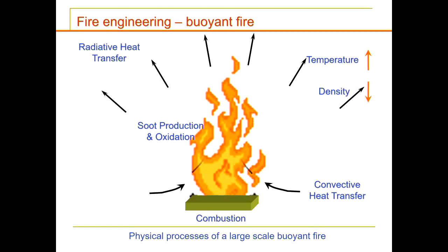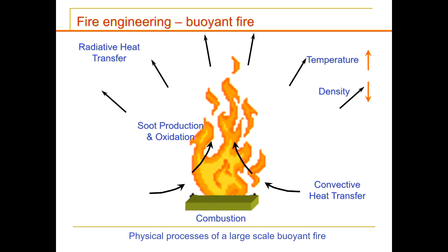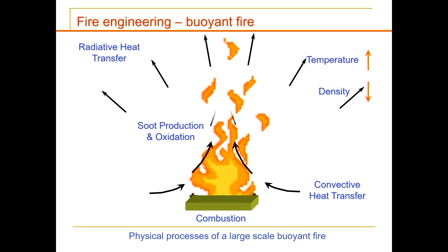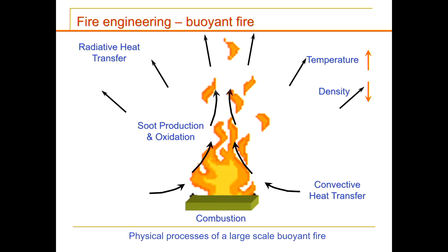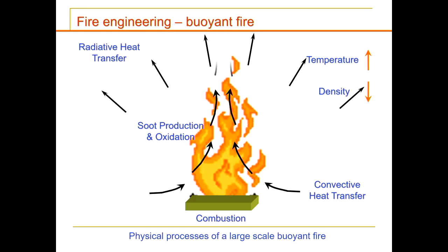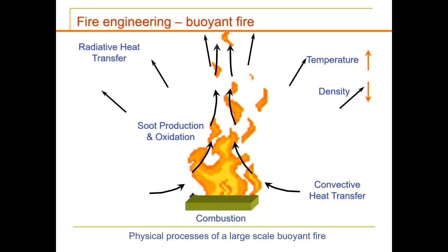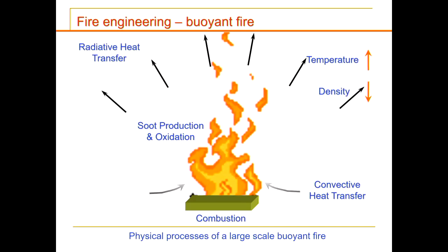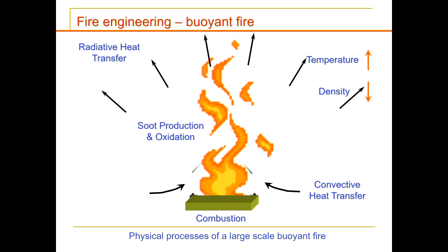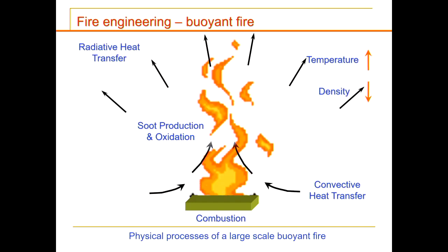Because the smoke layer is radiating the heat due to the soot. That also brings to a point that because of the smoke layer radiating away from the fire source, other materials will start to degrade and eventually they will burn. That's where flame propagation comes in. That's why eventually this whole lecture hall will be engulfed with fire. It's the mechanisms behind this that is important.